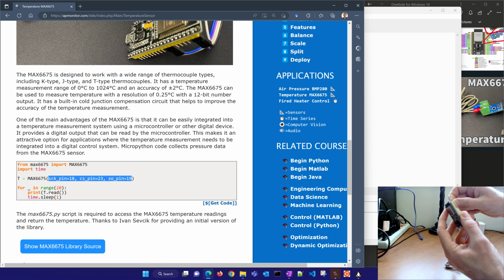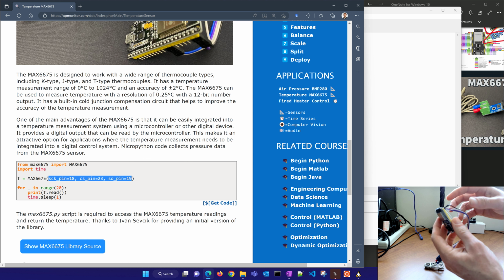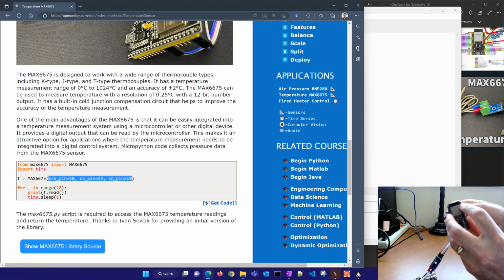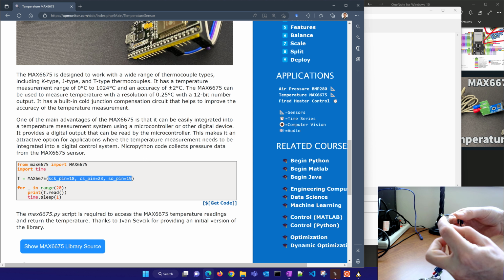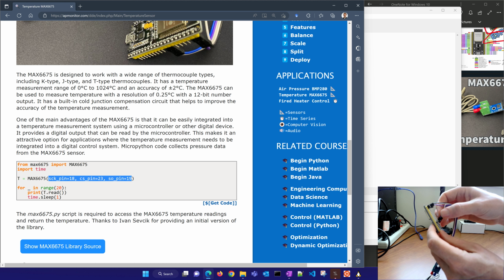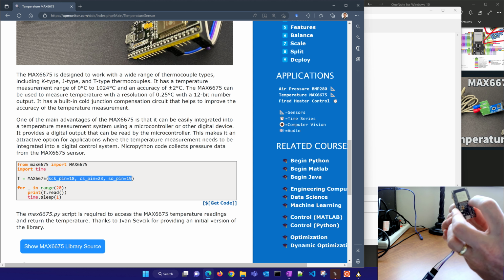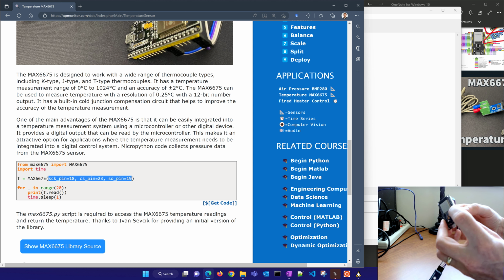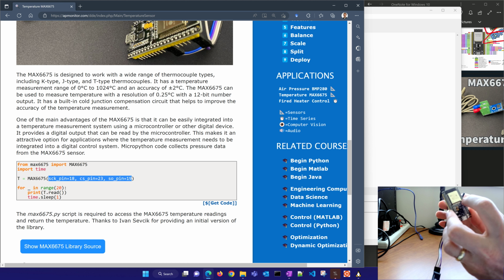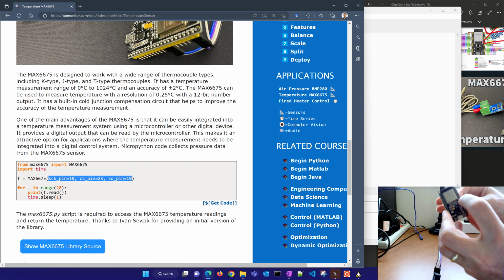So I'm just going to connect it here for my white and my black, and then I need to connect the select, the CS. I'm going to connect that here to my G23. So the purple one, I'm going to connect that here to 23. And then I have two more that I need to connect, and I will connect the clock to pin 18. Okay, so that's going to be my gray one, my clock. Let me see if I can find 18 here. Okay, there it is.